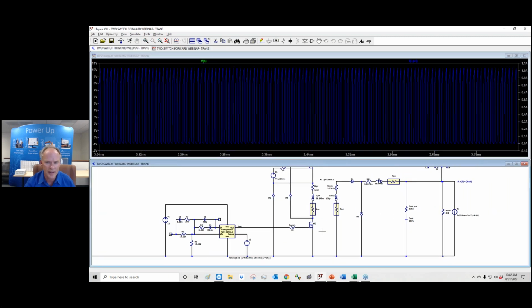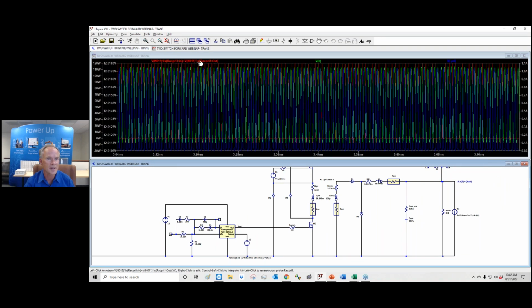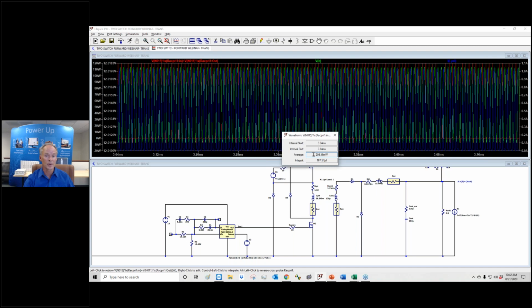Now let's go straight into looking at that AC resistance again. Right there. So these are our AC losses. Click on that. Now we're down from 1.8 watts to 200 milliwatts. This is almost a 10 times improvement just by layering and doing a different layer count. So yeah, proximity loss is really intimidating, but these are powerful tools that it gives you.